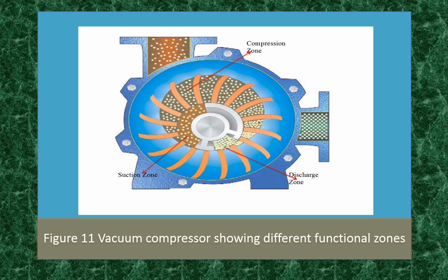Another important type of rotary pump used in the industries, particularly refineries, petrochemical and process plants, is the liquid ring pump. One of the most widely used methods for pulling vacuum is by use of a liquid ring vacuum pump. Liquid ring pumps are pumps in which a liquid ring is formed from the surface liquid and serves to transmit the energy required for compression of gases and vapors.